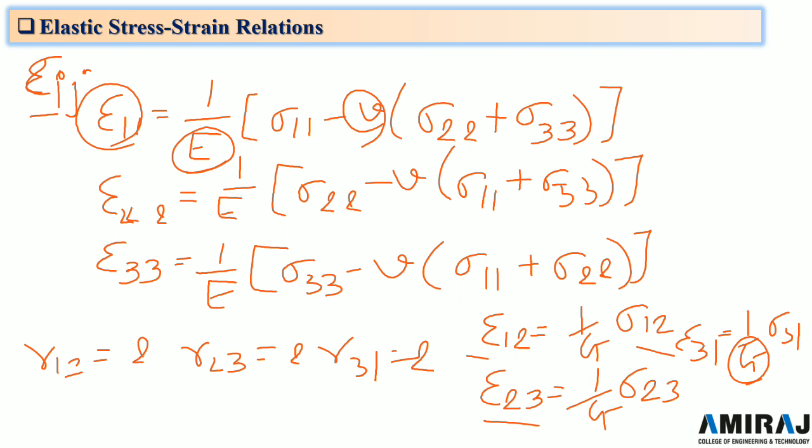We also define the bulk modulus, capital B, as the ratio of pressure to the relative change in volume of the body. Out of the 4 elastic constants E, G, B and mu, only 2 are independent for isotropic linear elastic materials, and in fact all 4 constants may be written as a function of the 2 elastic constants lambda and mu.